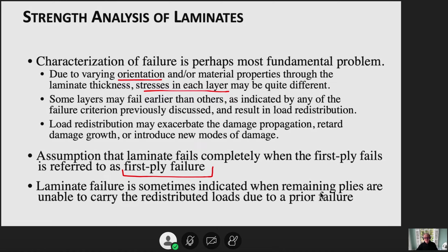And then if the remaining layers are carrying the loads, this will be something like a load, say P, versus displacement. So material will be behaving linearly. First matrix cracking happens, and sometimes you don't even see it, so you keep going straight, until the first fiber failure happens, then you may actually start seeing its influence, that this starts dropping or moving in other directions.